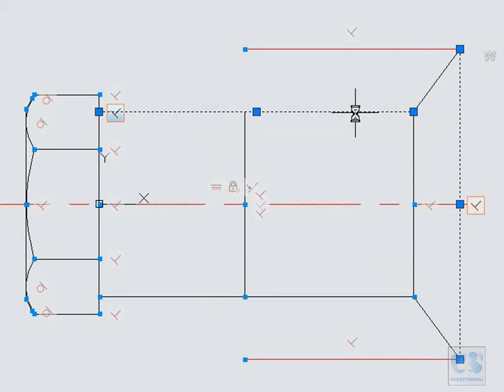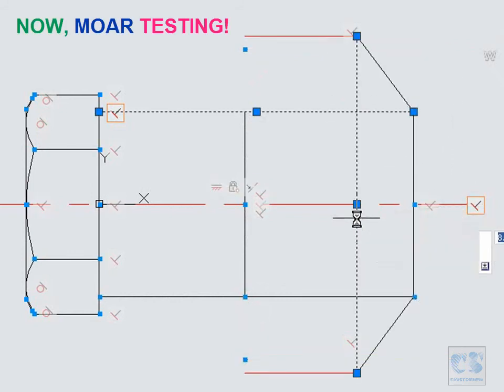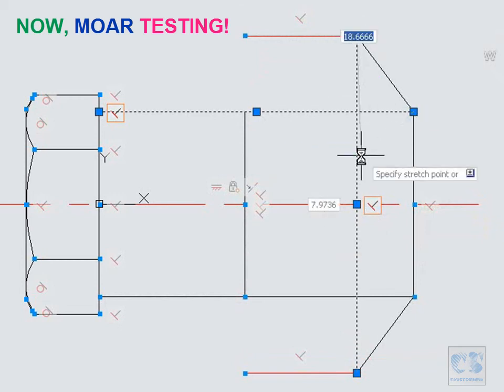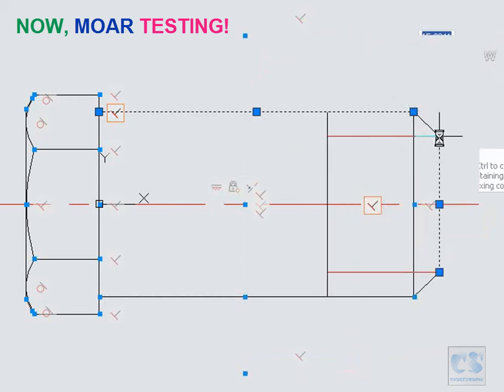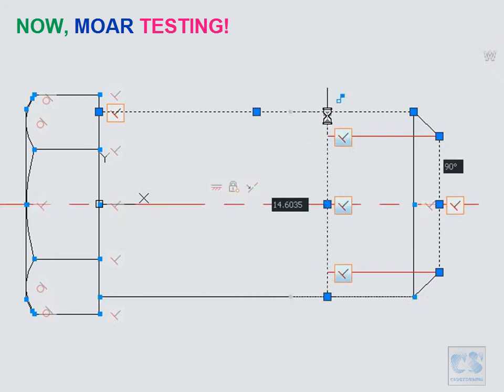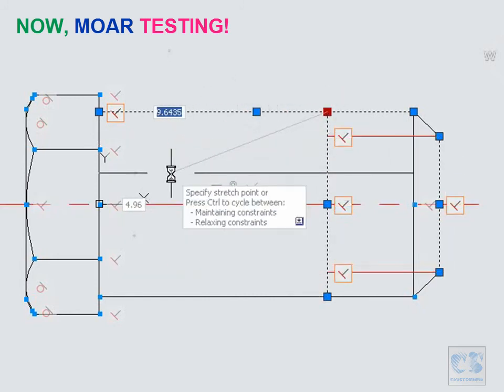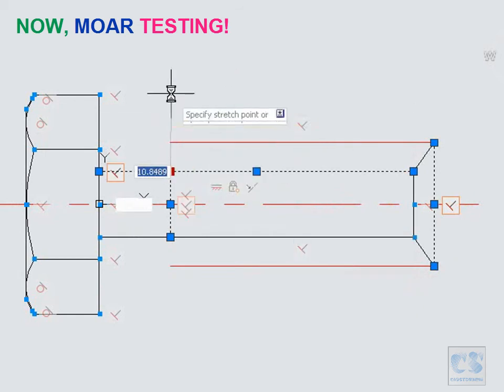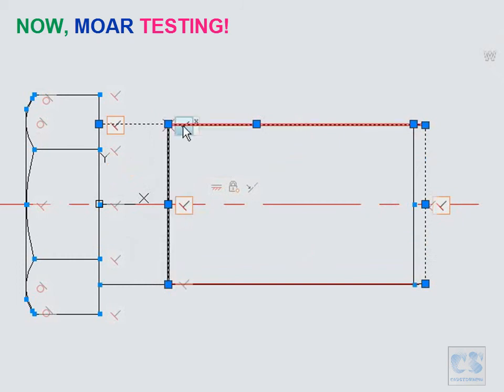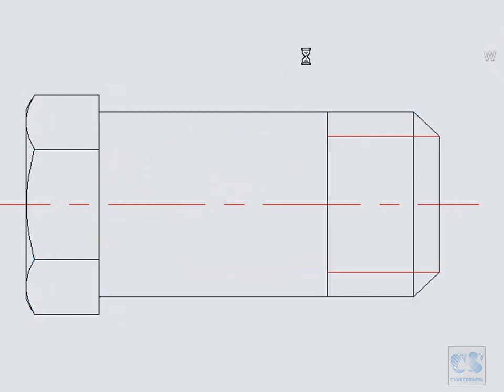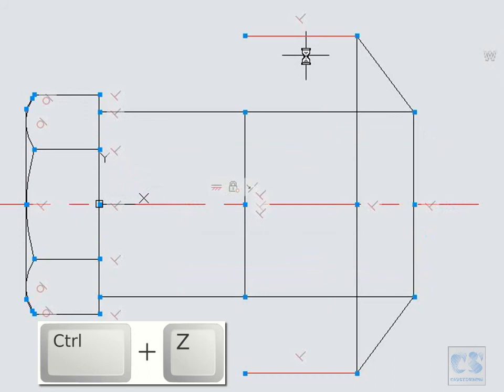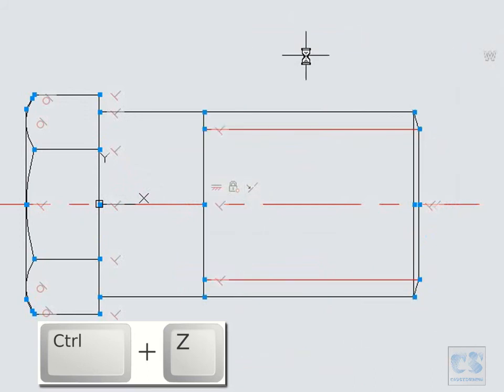You are going to have to do something to keep them in the proper location and orientation. But at least here, the endpoints stayed aligned with the threads end lines. Feel free to test your model however you want. This is how you will make sure that everything is working as it should, and eventually catch any mistakes you made and find what constraints are missing. Now enough playing around.